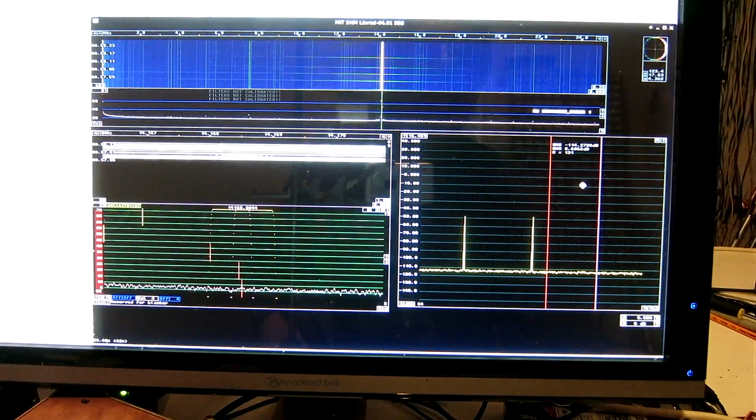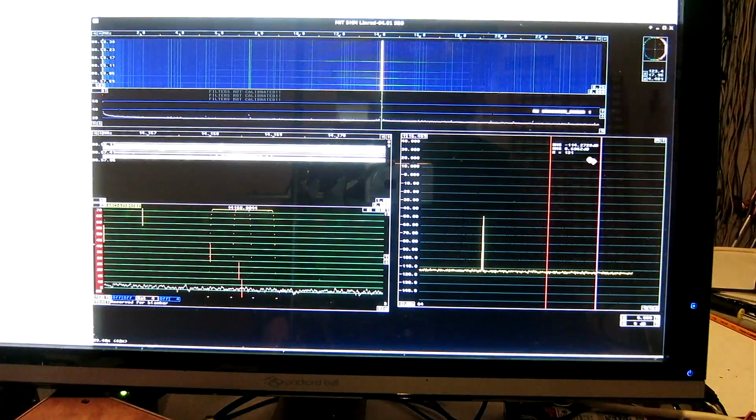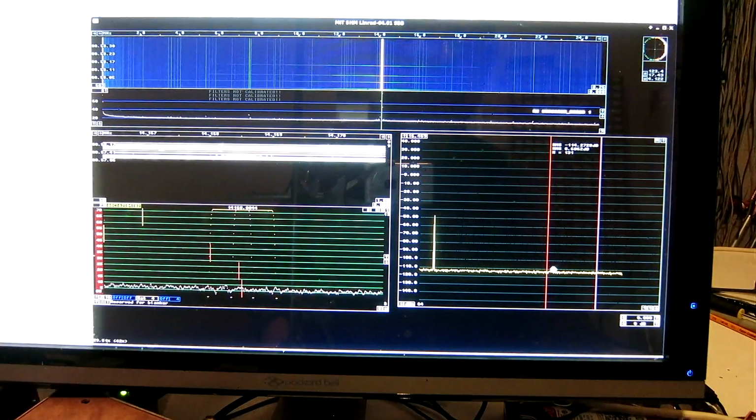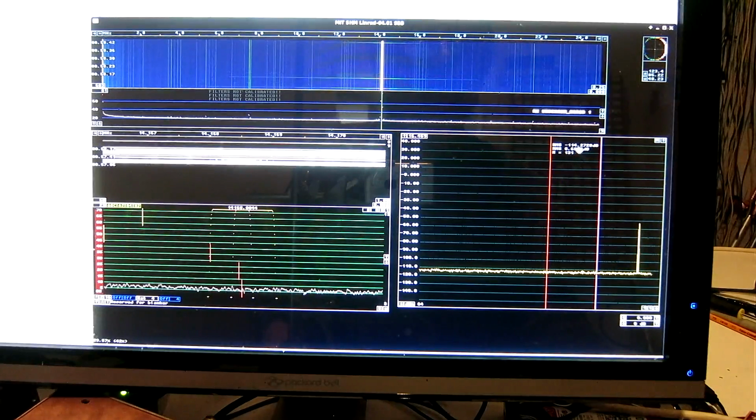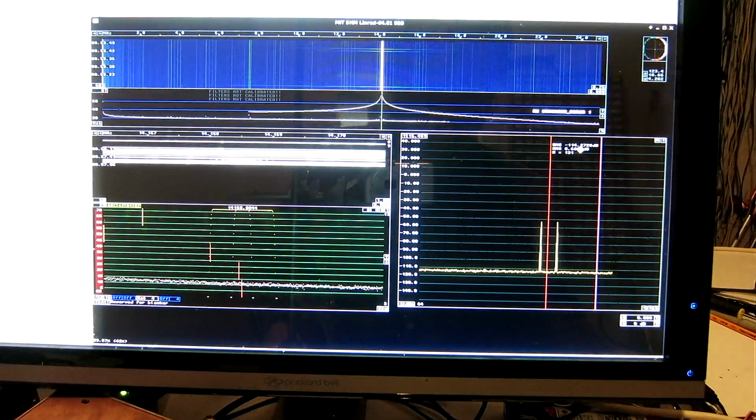And that is perfectly okay, because here you can see RMS, that means the standard deviation for a single measurement here is 0.6 dB. Now I made 100 measurements, which means that the error should be about 10 times smaller, or 0.07 dB.